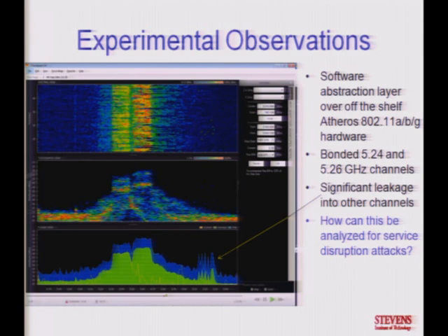Now, this picture here, this portion actually shows the actual signal power. And it is superimposed, don't compare them on scale, it's superimposed with the leakage. What happens is we have two stations, one operating in the 2.4 band, and another at the 5.9 band, which these two bonded. Both are transmitting simultaneously, and we are seeing what is received at the 2.4 band. So here this shadow shows the leakage power.